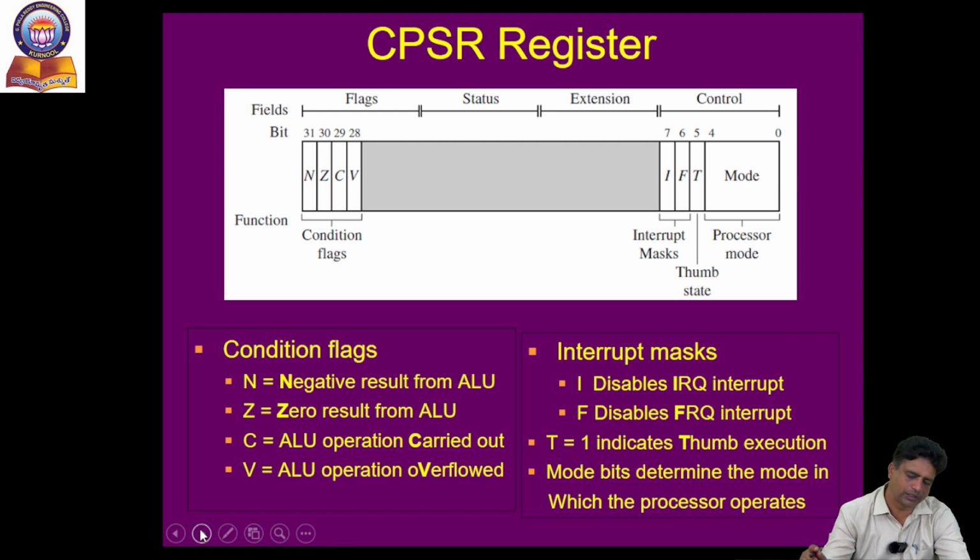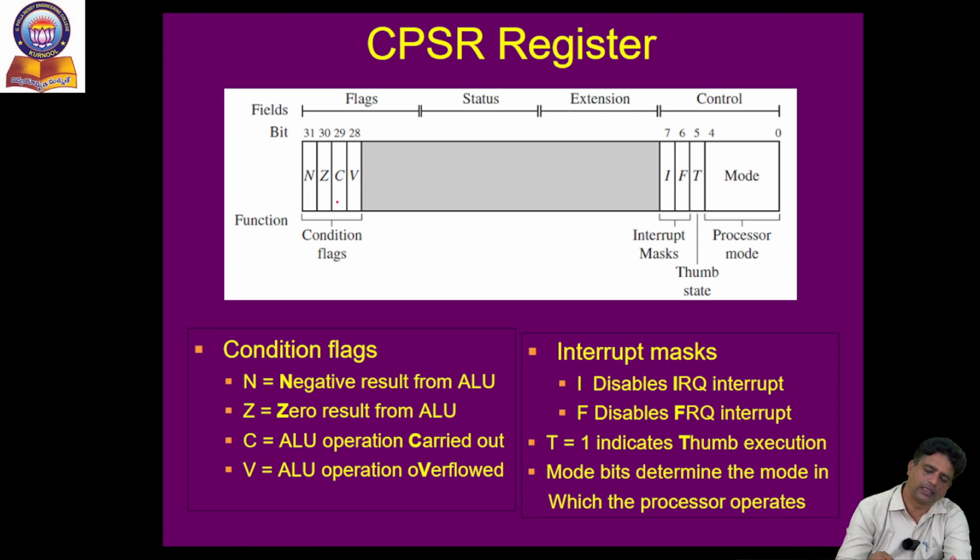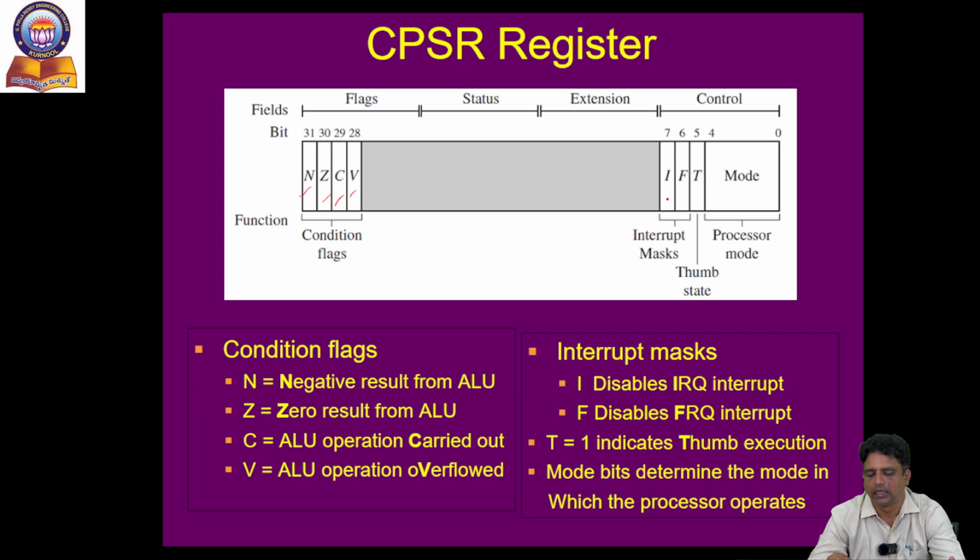One more prominent register we find is the status register. 32 bits are dedicated for the CPSR register for the ARM7 version, out of which the most popularly utilized arrangements are represented in the image here. Many known names are there, like carry, zero, sign, that is negative or positive, overflow. Some other names: interrupt request, non-maskable request, FIQ, fast request, thumb mode.